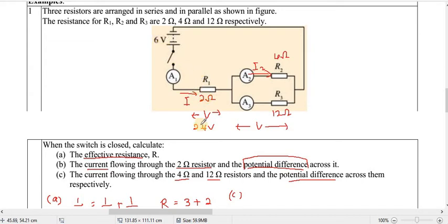6 volt minus the 2.4 volt, or 6 joule minus the 2.4 joule, so you get 3.6 joule, right or not? So that means the charge that passes through here will do the work of 3.6 joule. Passing through here also does 3.6 joule. So that means this potential difference is 3.6 volt. So you see, you get the potential difference here already.